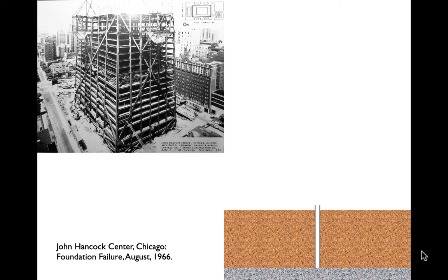And what the contractor proposed was that after filling up those tubes, they wanted to pull the tubes out. Once the concrete had cured, it would pull the tubes out. Now, this can be done. It means that you have to put a form release on the inside of the tubes, basically lubricating the inside of the tubes so that they don't stick to the columns. What had happened was they hadn't done a great job of lubricating the tubes, and in fact had tried to pull the tubes too quickly.